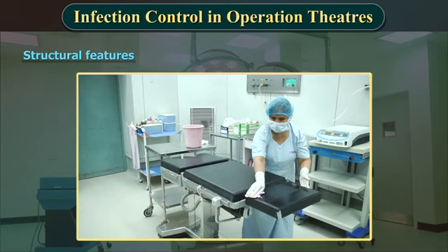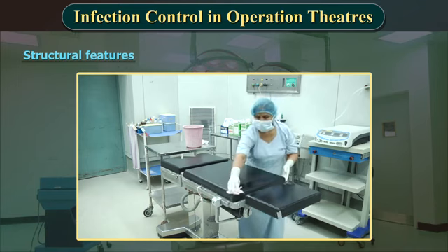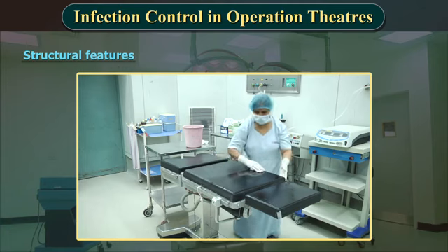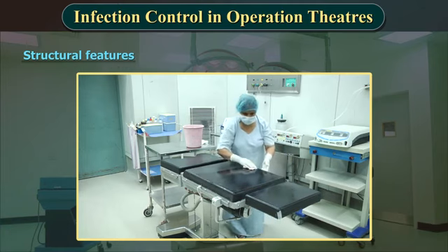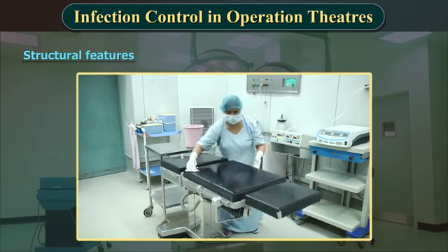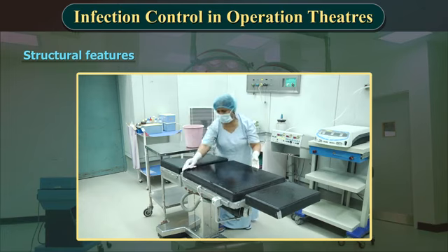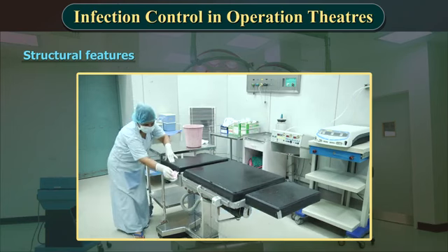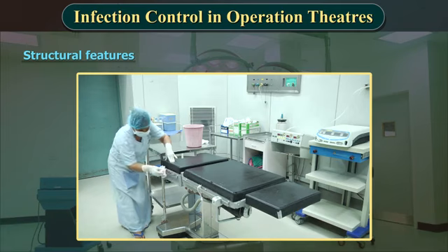Moreover, in designing an operating unit, the choice of surface finishes and structural features is of great importance. Surfaces should be easy to clean in order to facilitate infection control. Design, layouts, fittings, furnishings, floor coverings, and finishes will have a significant impact on the cleaning of the unit. Ledges, corners, and all other surfaces that are difficult to clean should be minimized.